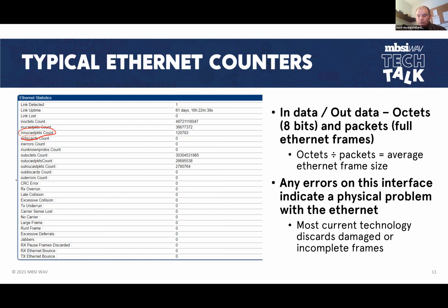Receive overruns. When I have that cloud of receive constellation, did the receiver take and make one bit into two or more? Do I have more bits in my frame than ought to be in the frame? So that would be called an overrun if that were the case. Do I have a frame coming late? Do I have a reflection or multipath in my analog path? That would be late.